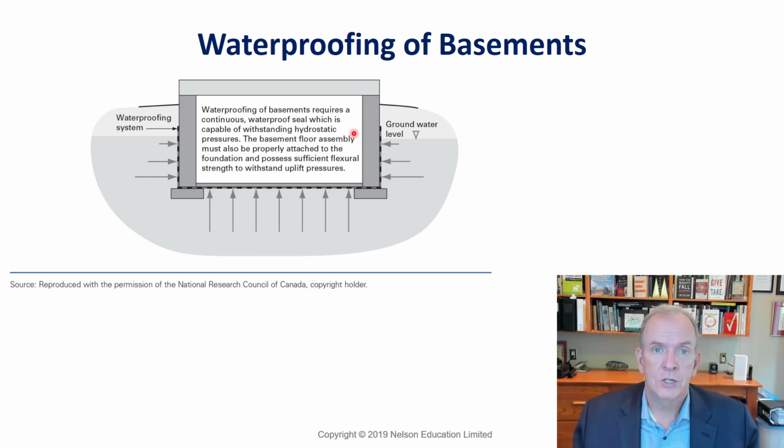And what happens in construction, to be honest, is people get away with things. So they do it lots without putting any bracing, and they get away with it. Maybe the backfill was pretty dry, right? Didn't pour rain on it, and there weren't conditions that created the pressure. But then after doing maybe 15, 20 houses, you do one and it's very wet, you backfill it, somebody runs a bobcat along the side or the edge, putting more pressure on it, and then the foundation wall cracks, and not only does it crack, it shifts, and then you've got one heck of a big mess to deal with.